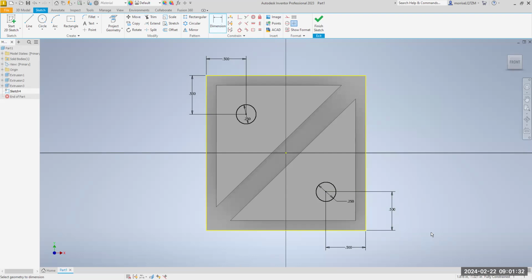All we've done is we've milled around the block, and we went across at a diagonal, and we're going to use the end mill to make 2 holes. They're not even through holes. They just go down a certain depth and that's it. Make sure you dimension these holes properly. They are 1/4 inch in diameter and they are both a 1/2 inch from the corner, the horizontal dimension and the vertical dimension.